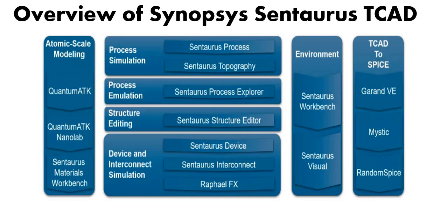In the device simulation, advanced physical models for quantum effects, ballistic transport, tunneling process, stress, hot carrier injection and other transport mechanisms will be optimized. So we can see that Sentaurus device is the main simulator that handles all kinds of electrical behavior for a device. The next one is interconnect simulation, which is done with the help of Sentaurus Interconnect, which studies the electrical properties of interconnects.